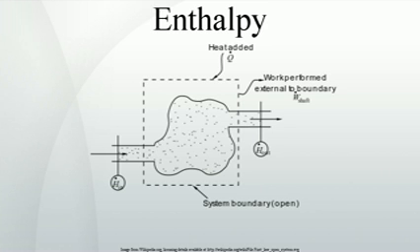Compressors. Fig 3b is a schematic drawing of a compressor. A power P is applied, for example, as electrical power. If the compression is adiabatic, the gas temperature goes up. In the reversible case it would be at constant entropy, which corresponds with the vertical line in Fig 2. For example, compressing nitrogen from 1 bar, point A, to 2 bar, point B, would result in a temperature increase from 300 kelvins to 380 K.